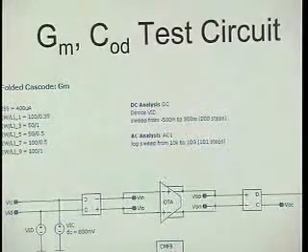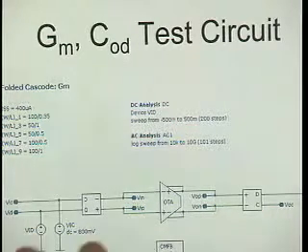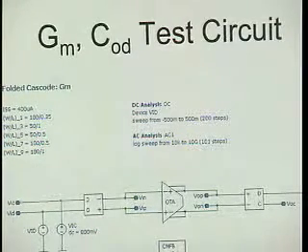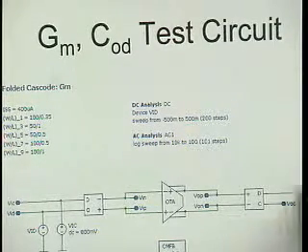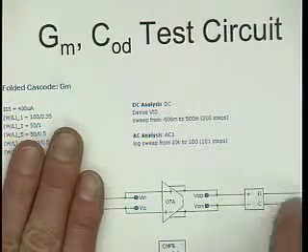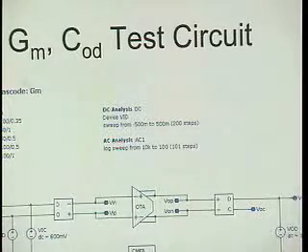Same thing, the output capacitance, right? Big pain in the neck. Of course, there is a load capacitor there, and we made it just large enough that it's 2 picofarad. We know that, but there are also the junction capacitors of the switches and other stuff hanging there. Well, how much really does it add? It's difficult to get that. The easiest thing is to simply measure it, and for that, again, what we do is drive the output. In this simulation, we drive the output of the amplifier, and we look at what current flows into it. The ratio of voltage over current is impedance, right? Or current over voltage is capacitance, if we also divide by frequency.